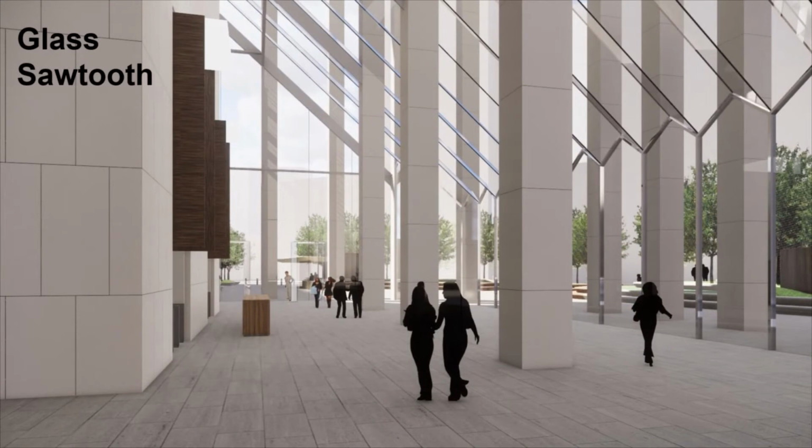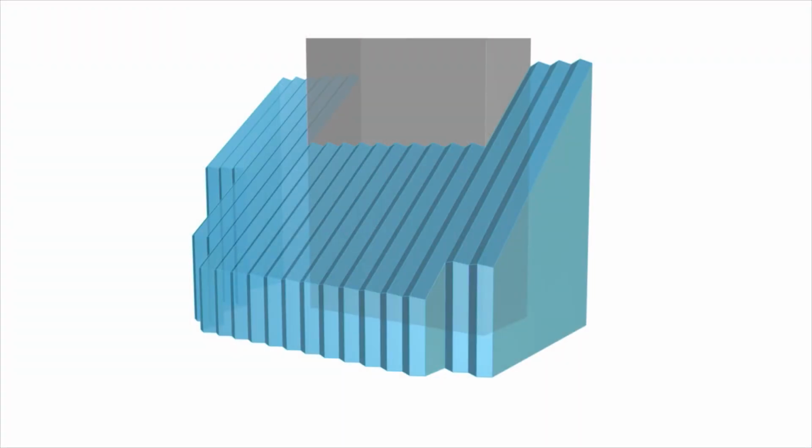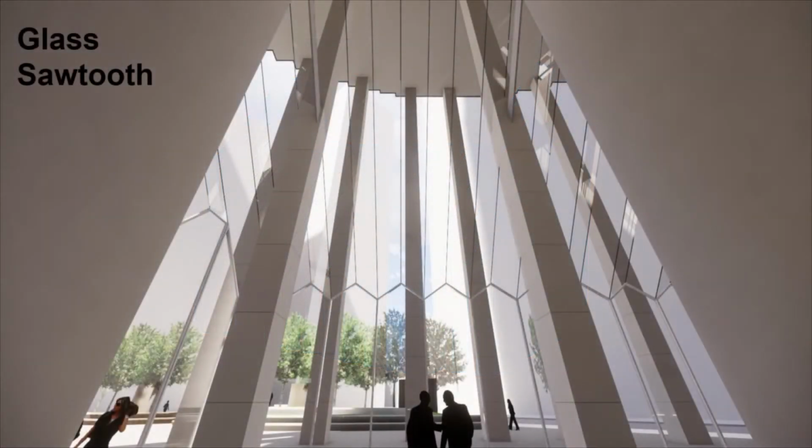And then the third option that we did a bit more exploration on was the idea to use the glass in a geometric configuration that would help span on its own. So this sawtooth pattern, which is shown here, mobilized the glass panels so that they were actually spanning on their own, and there was no traditional glass beam or glass framing required. And again, this really opened up the structure to be as transparent as possible.